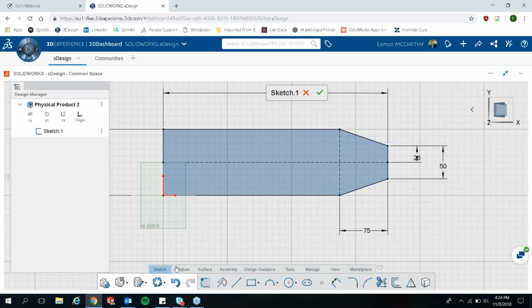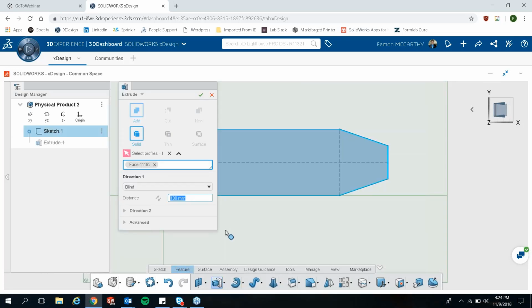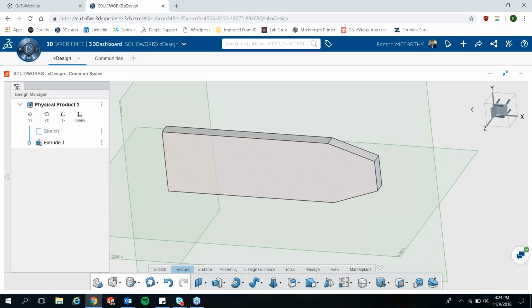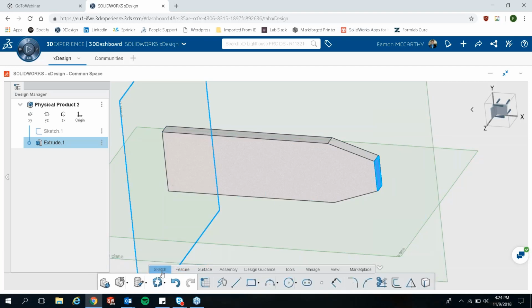We're going to extrude this out, make our thin panel. We're going to make the thickness of this 20 millimeters. Now on the end here, I'm going to make a small circle and insert it into the body of the satellite. This is going to be our mounting location, so again we select the face. We're going to start a new sketch.